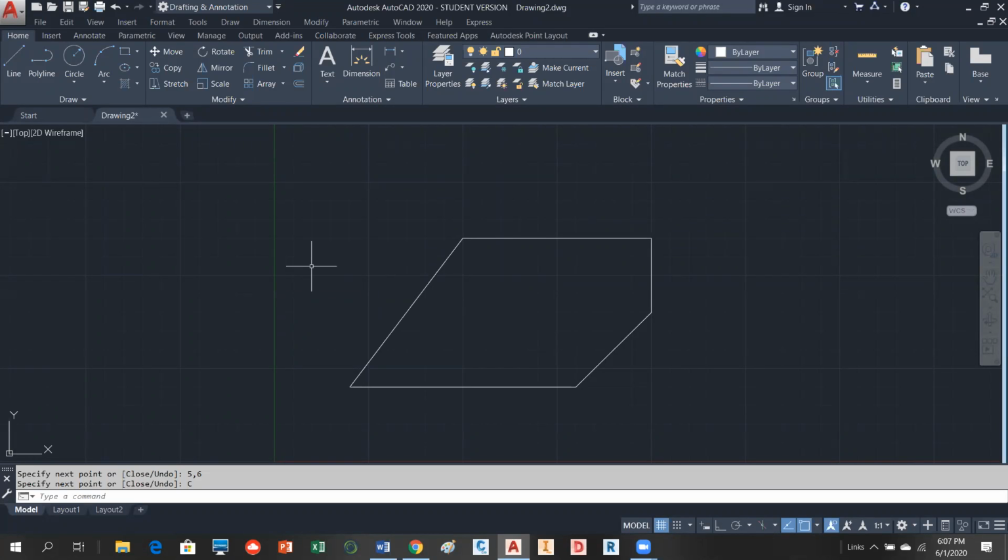So that's a bit of work. It's probably more than you need to do or want to do sometimes. So there's going to be easier ways to do things in AutoCAD. But we're learning a very rudimentary way of doing it, and this is going to be very powerful as you get into things later on. Okay? So we're going to redo this. I'm going to show you, we're going to do this slightly different. We're going to use a relative input as opposed to the absolute input. So we're going to still use rectangular coordinates, but we're going to do it as a relative mode.